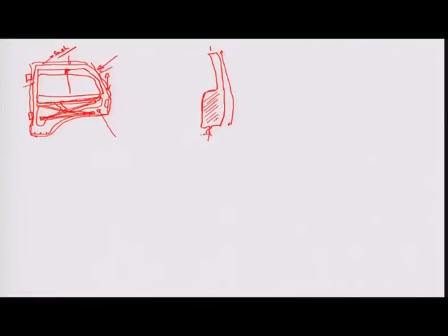The weather strip is connected in a manner so that it plays its role in terms of generation of pressure. There are certain lips which sit to the car body, okay, and the weather strip goes all the way round this periphery, as you can see here, and it might have more than two lips, completely made up of rubber, which would create a closing pressure of the door on the side body of the automotive, so that there is prevention of leakage which may happen.